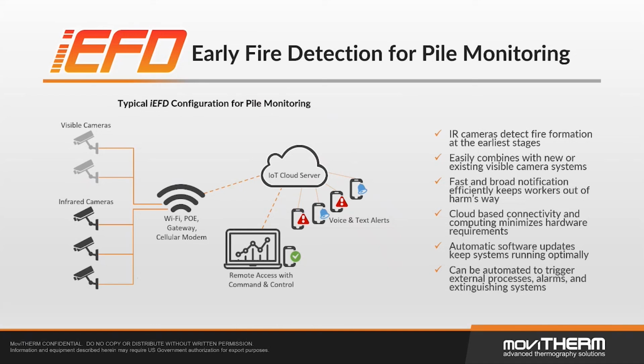But it's really, and we can also distribute our gateways. It doesn't have to be a central location for one gateway. We find sometimes that especially in large facilities, rather than having to run back the cables to a central location, which might cause a long cable run, we can also deploy multiple cellular modems and have our gateways closer to a cluster of sensors in the facility and have maybe 3 or 4 or 5 cell phone gateways. That way, again, you reduce the cable run and the complexity of the system.